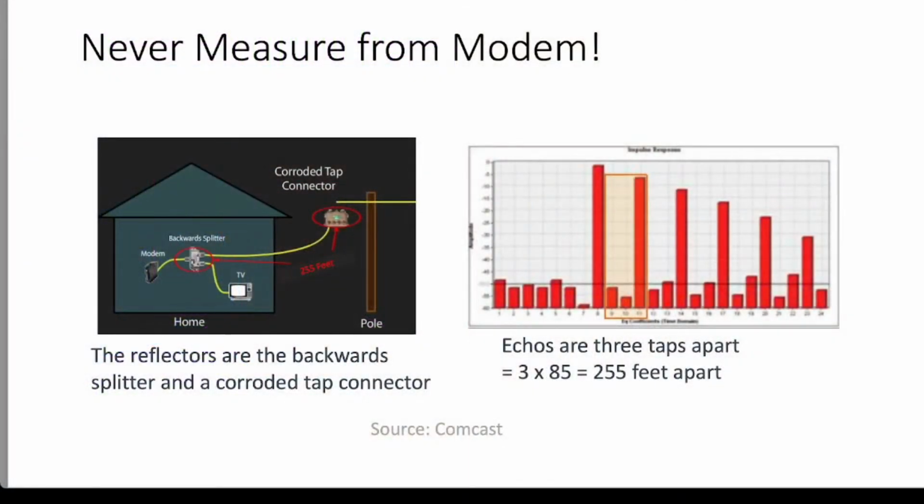Let's put the modem and the TV and swap them. What I can see happening there is the modem would have to overcome more loss for port-to-port isolation to get back to the CMTS, so it would transmit hotter. And because it transmitted hotter, it would find its way to the TV on the other connection, right? Because we're going to swap them. Right. And you'd probably have even worse reflections. Same cavity, but it would be much worse in power level.